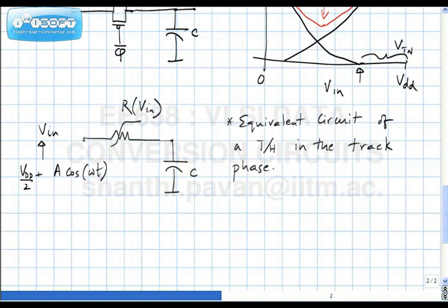As with all nonlinear systems, I'd like to figure out what happens when I put in a sine wave. If the system was absolutely linear, meaning R wasn't dependent on Vin, then can you comment on what would happen when I put a sine wave at the input? The voltage across the capacitor will definitely be shifted in phase from the input, but it would be a pure sine wave without any harmonic components, right? Because of the resistance depending on Vin, what would you expect?